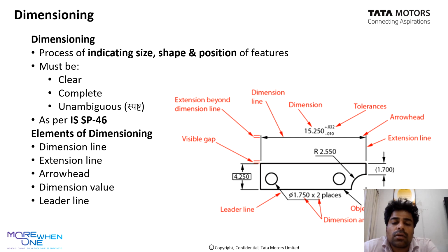The line that shows the length of that shape of that object should ideally not touch the main object drawn directly. Also, it should be made of a light color. Why? So that we can distinguish between the real object and the lines drawn only for showing the dimensions. So you can leave a slight gap over here and make the rest of the line, and you can make this a dimension line. You can see on the top it is written dimension line.